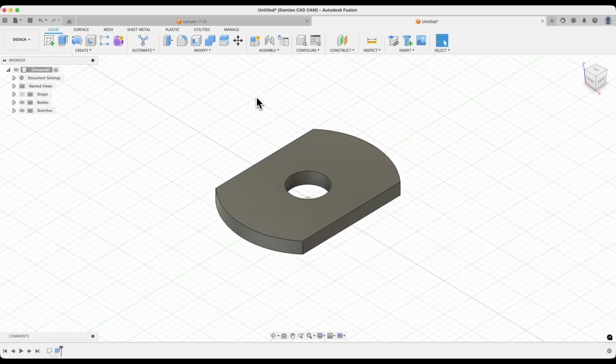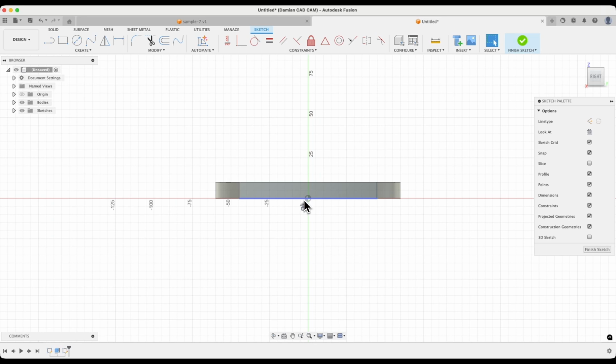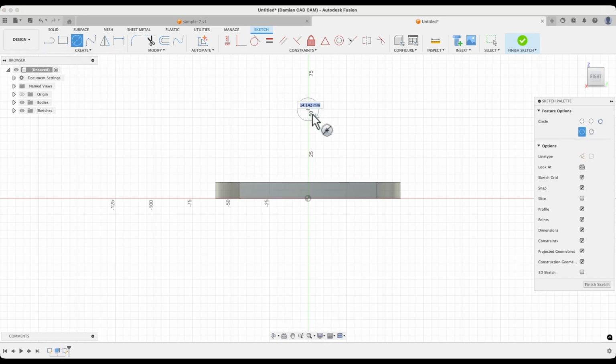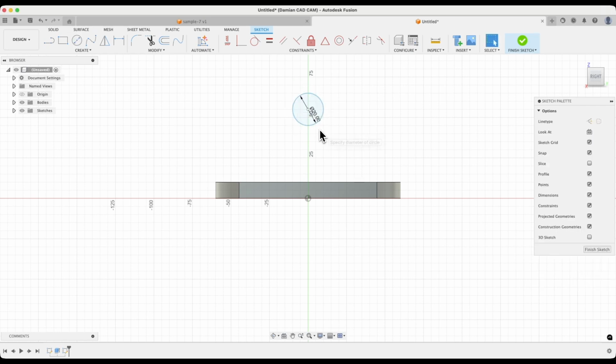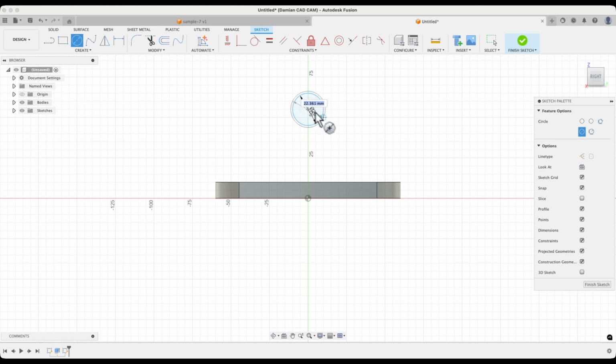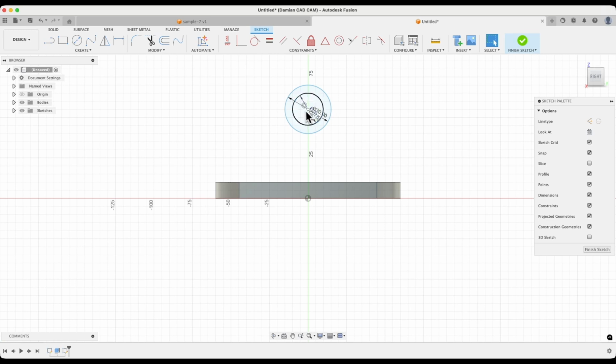Now we will create another part of the solid. Select this face and choose Create Sketch so that the face becomes the sketch plane. Draw two circles anywhere, one with a diameter of 20 mm and another whose center is at that point with a diameter of 30 mm. As you can see, the positions of these circles are not defined, and we will do it in such a way that the center of this circle is in line with the origin of the coordinate systems.